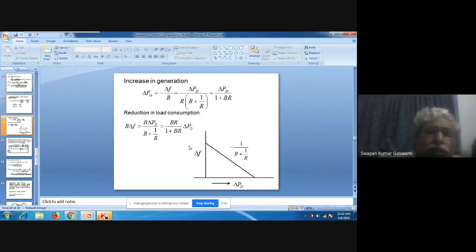See, during morning hours, you have fixed the operating frequency for your system. During morning hours the load is less. As the day progresses, load increases, and because of increased demand, it is certain that frequency will decrease. Frequency will start decreasing as the demand increases. If this happens, the system frequency will vary through a wide range.